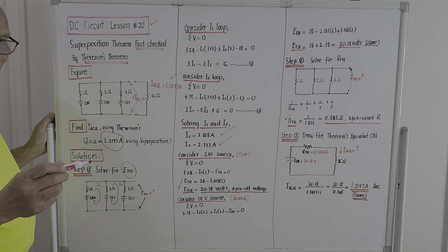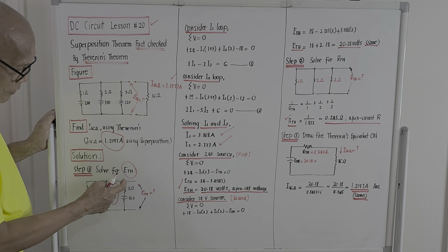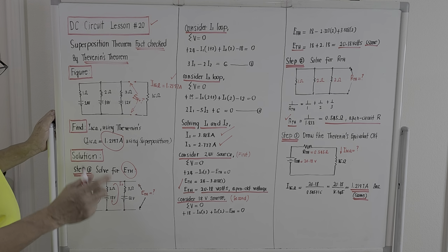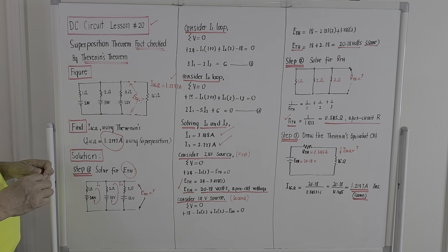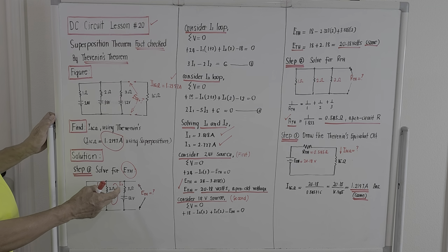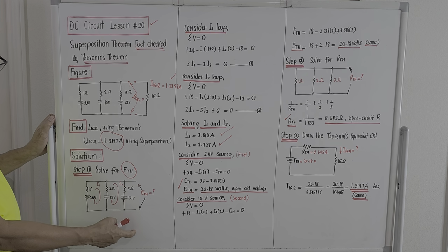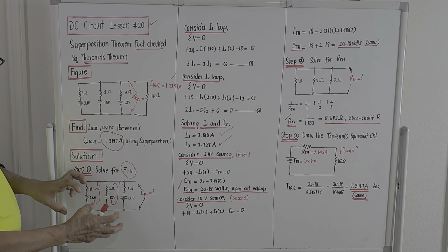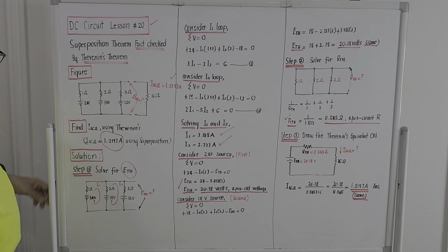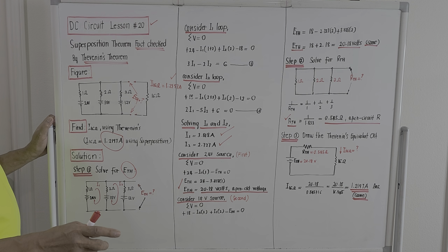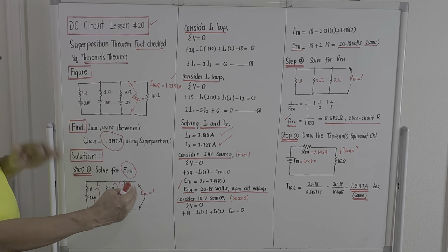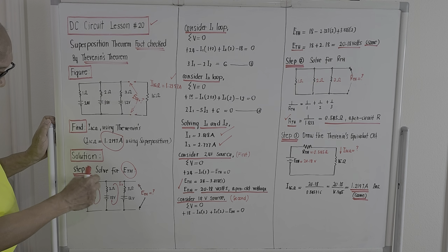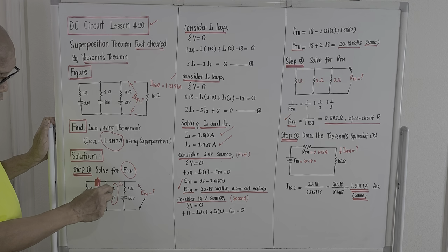To simplify the calculation of the open circuit voltage, I will first compute the circulating current, because if we disconnect the 16 ohm load with this given configuration, there will be a circulating current. I designate the circulating current on the first loop as I1, and the next loop as I sub 2.